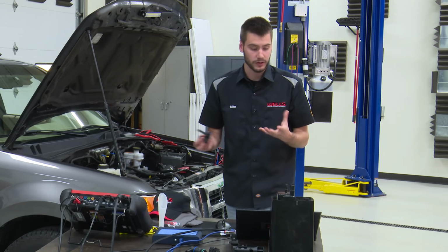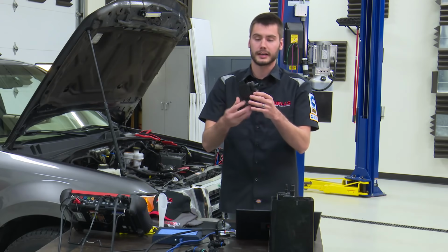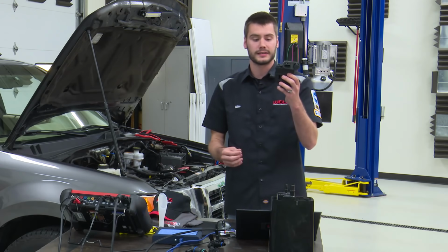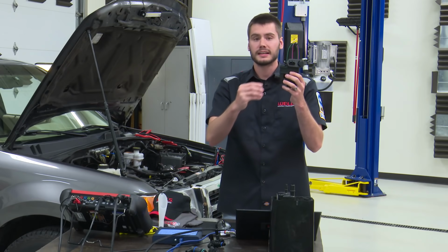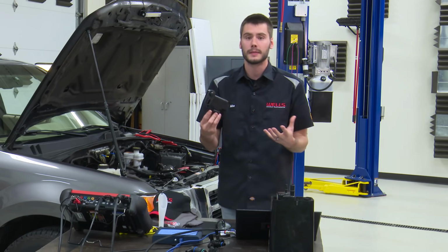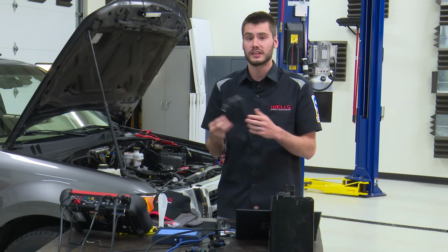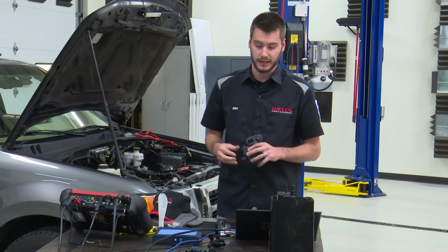So the back door on the system would be the vent solenoid. This would be a remote mounted vent solenoid. You would find this with a hose attached to it, connected somewhere back to the canister. This is going to hang out maybe in a fender well, maybe up above the transfer case on a Chevy truck. Location on this is usually under the vehicle, somewhere near the canister.